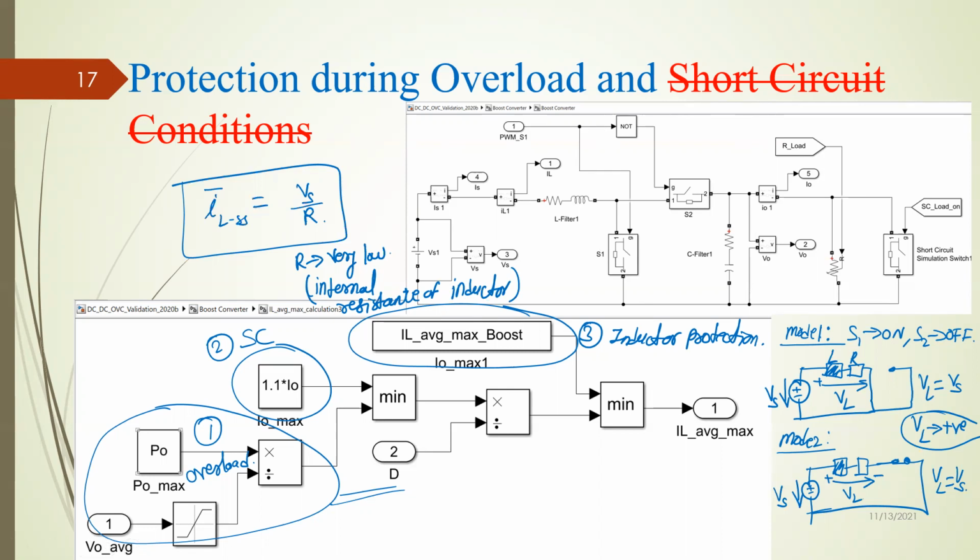So what can we do to protect our device? You have to disconnect your DC-DC converter from the load. So when you design your boost converter, it will be nice if you also use one switch here. So let's say a contactor, or it can be a fuse also. You can add a fuse or a contactor, and then you can turn the contactor on and off.